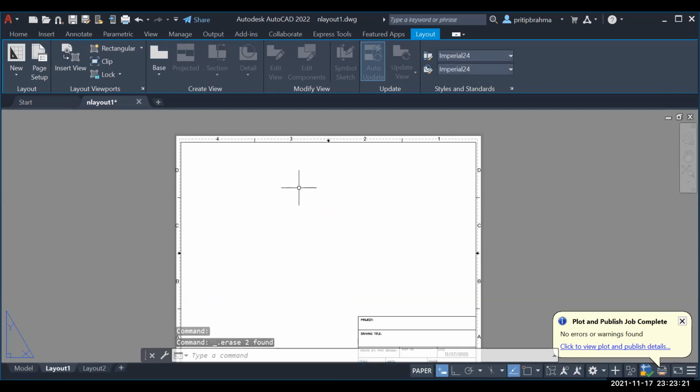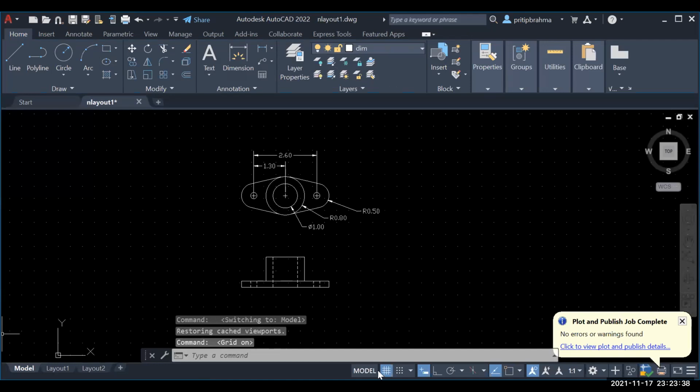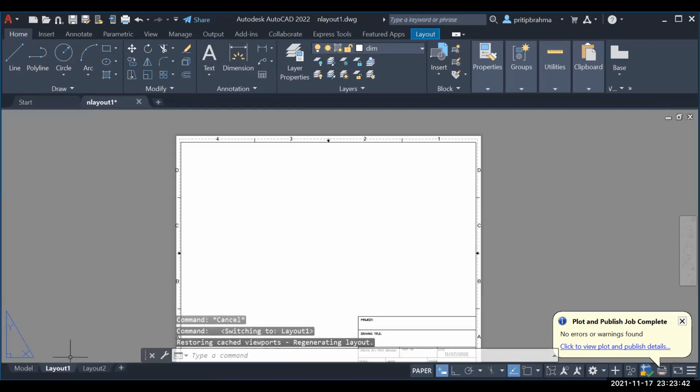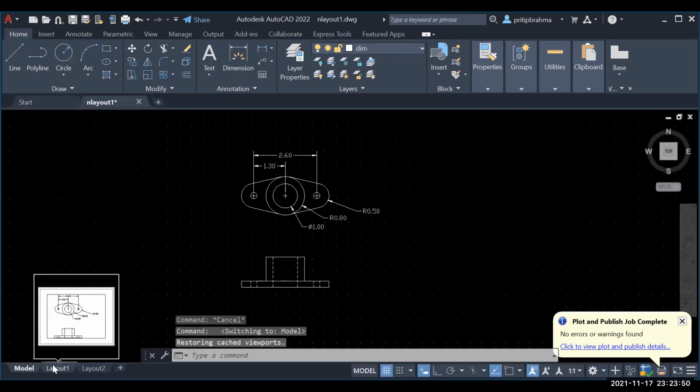I have a question. Yep. When I inserted a viewport, the grid showed up behind my image. Yeah, the grid will not print, but it does show up. I don't know why mine isn't showing. Oh, because it's off. My grid must be off in model space. So when my grid is on, it will show up here. Okay. But it won't print, so no need to worry about turning that on and off. Okay, I guess this one just was off. No big deal.